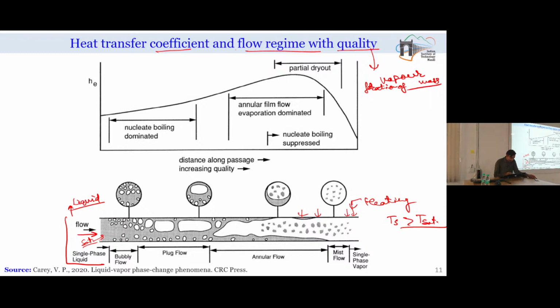Now, whenever this fluid is flowing, of course, at the entry point it will have some pressure and at the exit point it will also have some pressure. So, typically whenever we study internal boiling, we will have some delta P. Now, it may become difficult to understand how to define the saturation temperature. Of course, for exactly locating the thermodynamic state, we can refer to the local pressure and local temperature conditions, but globally if we have to define the saturation condition for the entire tube, we can simply take the average of this pressure to define our operating pressure, and corresponding to that we can obtain the value of saturation temperature.